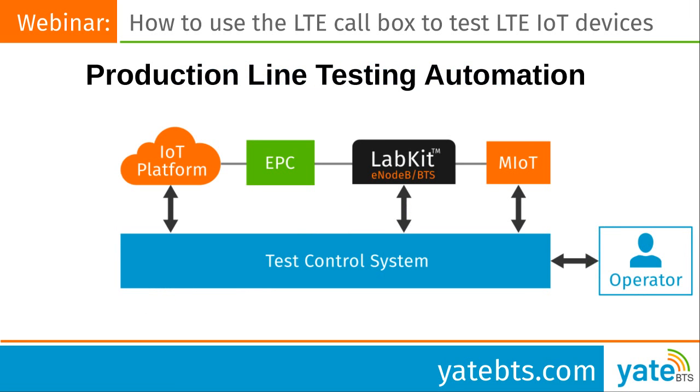The typical production line testing system is going to be automated. And here we have, working from the left, your IoT platform, which is probably cloud-based, whatever IoT platform your application works with, the EPC, your LabKit, eNodeB, and the mobile IoT device, the device under test. And then coordinating all this and sort of closing the testing loop, we have the test control system, and then the operator.